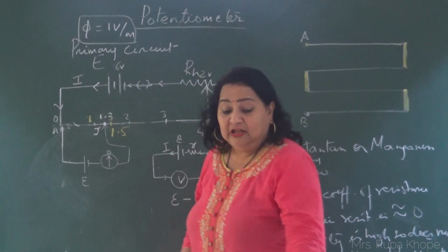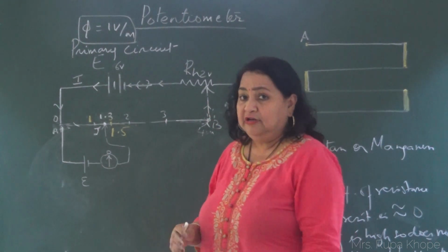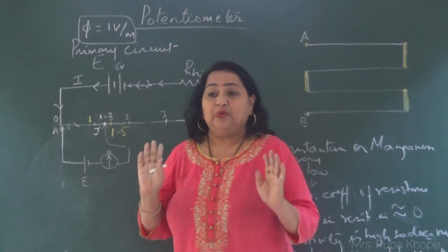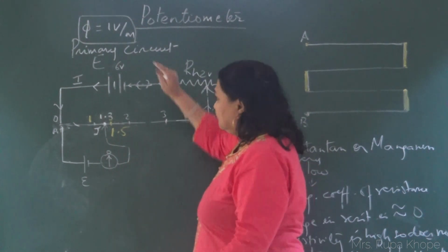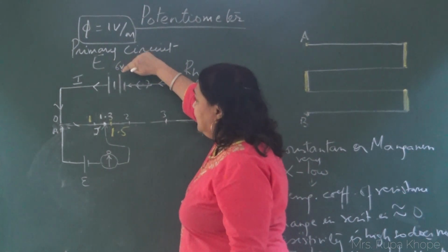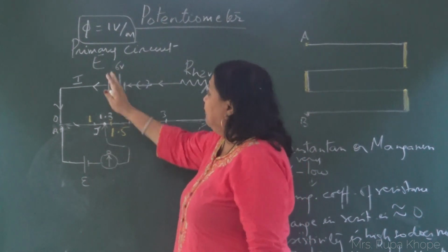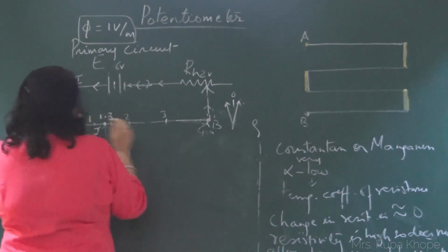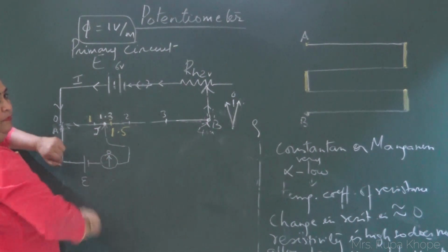That is one thing. Now we need to see two important points we have to learn. That is, we need to know the conditions so that this potentiometer will work. Point number one, this particular EMF has to be greater than this. That is understood. But it is not the only condition. Actually, the voltage across AB has to be greater than this. This is more important.